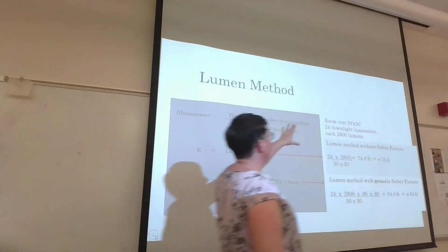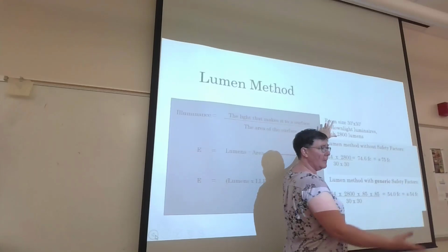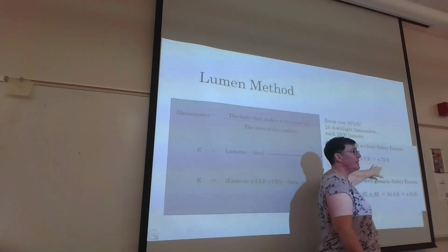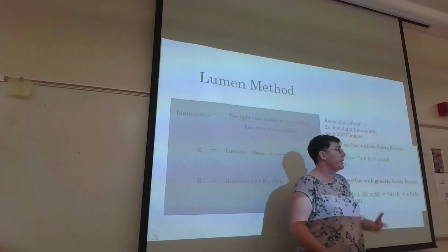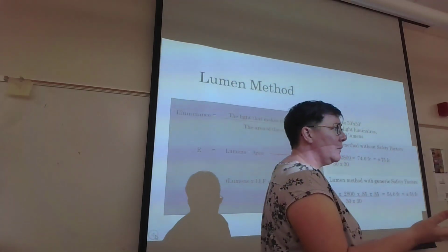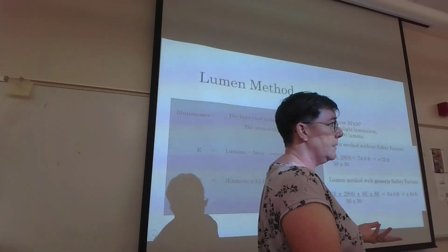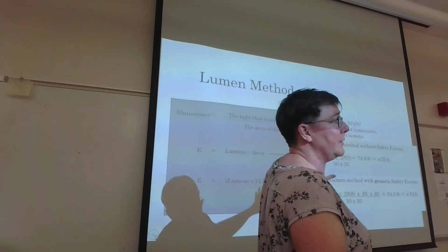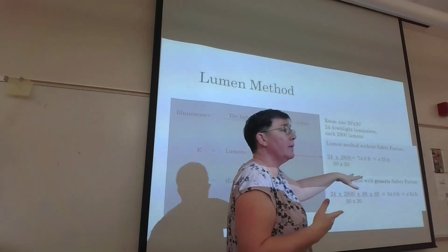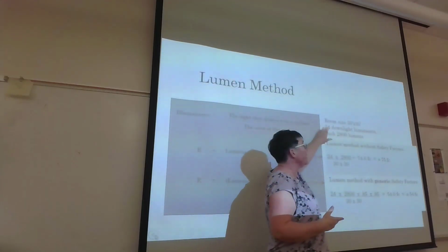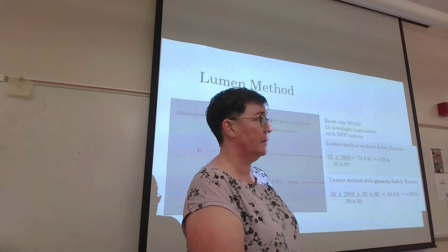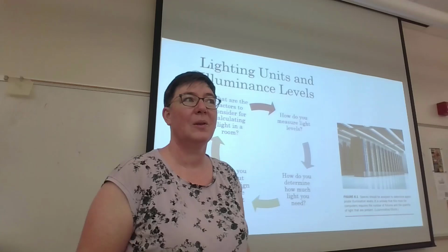Yeah, so the question was, with this design scenario, this is what we want. We think, but how much light is it going to provide in that room? Does it provide 75 foot candles? Ideally, but no. In reality, we have to assume that those light loss factors come into play, and it's only going to provide 54 foot candles, so you have to design for that. Then you have to compare against your target illuminance. How much illuminance did you want in the room? Did you want 50? Did you want 80? We didn't tell you for this particular problem, but that's the next step. You would ask, was this the right design? And if 54 was not enough for you, then you need to either add more luminaires or change the luminaire specification to something that gave more illuminance, more lumens. So if I wanted 50. All right, let's keep going.